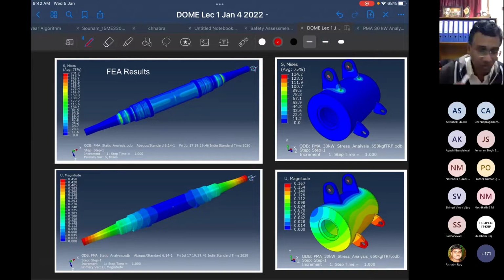So what do I want you to remember from all of this? Anytime you're doing a machine design, once the technical specifications are provided to you, you start by figuring out how to achieve the desired kinematics, how to achieve the desired motion of items within the system. Then you use free body diagrams to find out the forces and moments acting on each of the components. Then you have to propose some part drawings for things which have to be designed from scratch, and you select some items for whatever has to be selected.